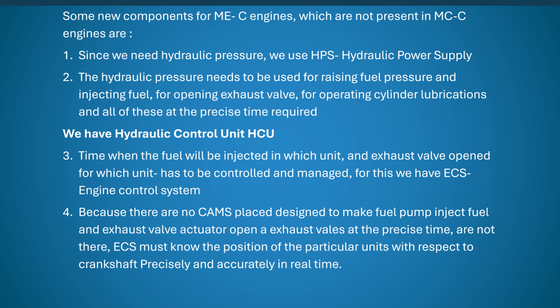It cannot open the exhaust valve when the piston is at the bottom of the cylinder liner. So precise timing is required. That is done by the engine control system, which will tell at what time fuel is to be injected and at what time the exhaust valve is to open. Accordingly, the HCU will allow the hydraulic pressure to move and carry out the task.